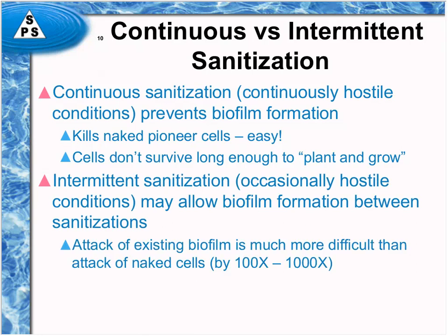Whenever you have an existing biofilm that you're trying to attack with a sanitant, it is much, much more difficult to kill than are the naked cells that are being attacked during continuous sanitization, and much more difficult by 100 or 1,000-fold more difficult. And that's not an over-exaggeration. The biofilm slime on the surface, particularly for chemical sanitization, makes it a very, very strong impediment to the penetration of the sanitizers.